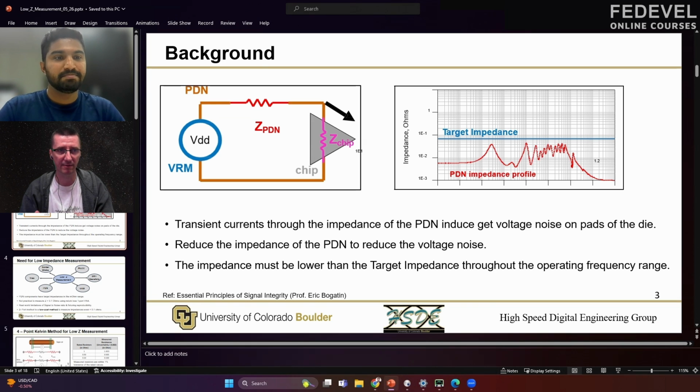So this means basically we still will have some kind of voltage drop on this ZPDN. Yes. But it's going to be constant. So if we need, we can, for example, increase the voltage a little bit or something. The voltage drop is not going to be constant, but it needs to be below a certain level, for example a plus or minus 5% tolerance level. Yeah, okay. If that's the case, we need to have the impedance Z such that it can be anywhere, but it should be below this target impedance line.